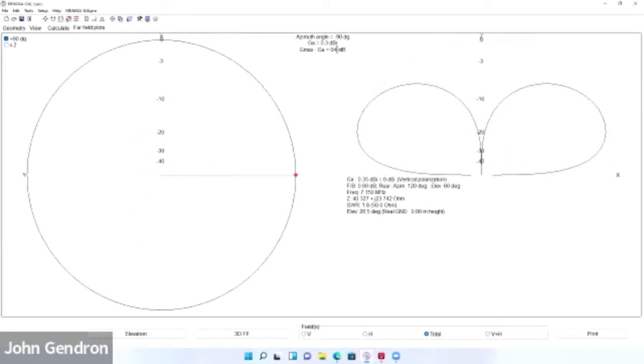Okay. Now, when we start talking about antennas comparing to, you'll have a difference in dB, and you're going to talk about it in dB, right? Not dBi. dBi is strictly gain against a set model, which is the isotropic radiator. Okay. So now when you look at the left side of the equation, right, we've got the